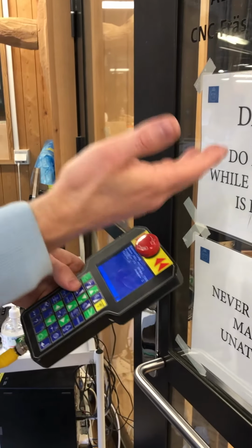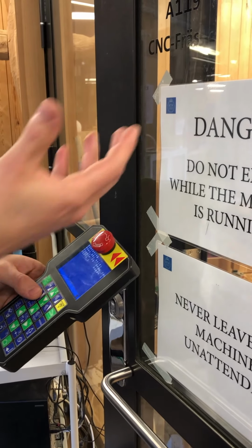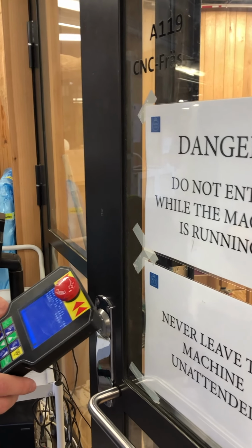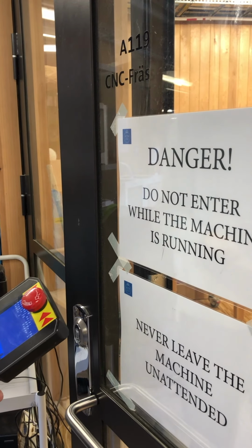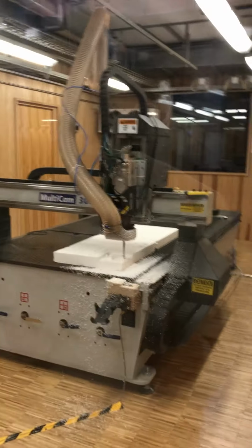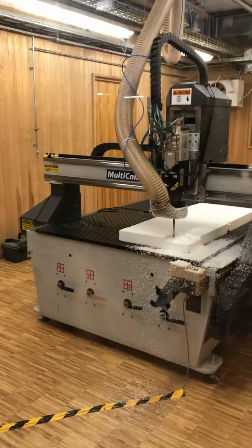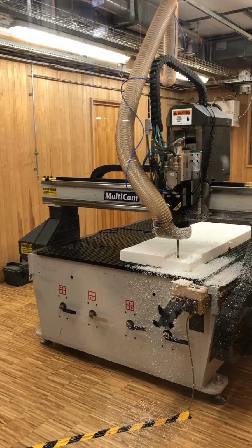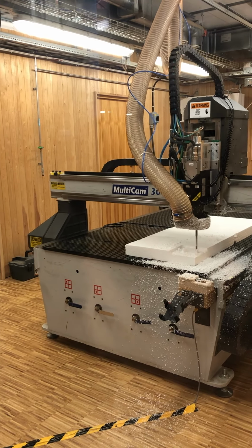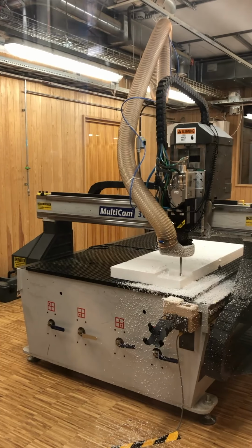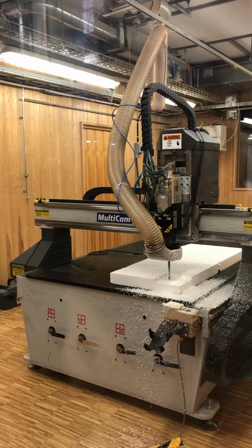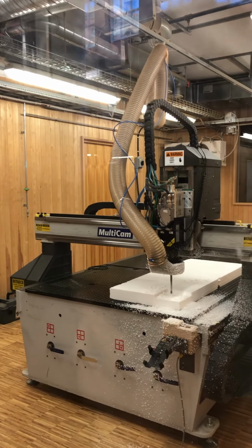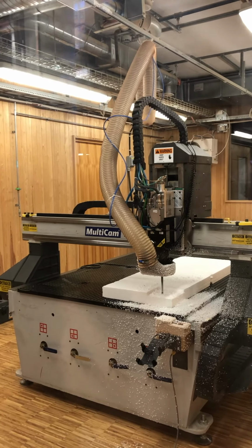But from here, I can't say that I can see the result and evaluate it. But it looks like it does its way in the way one would expect. And here one can see that when working in really soft material like styrofoam, it's really good if you're doing your first CNC job because it's really forgiving. But you might also have seen that thin shapes like that just flew away. If you're doing this in wood, then of course there would be more rigidity to the material.